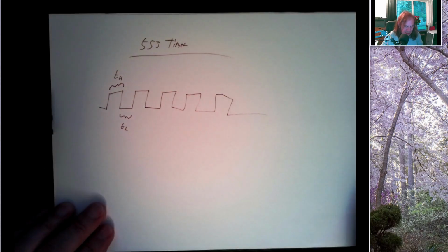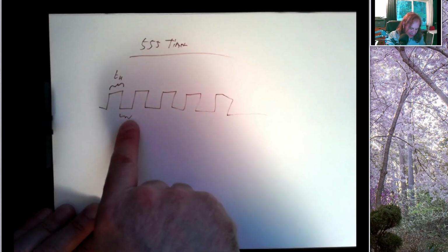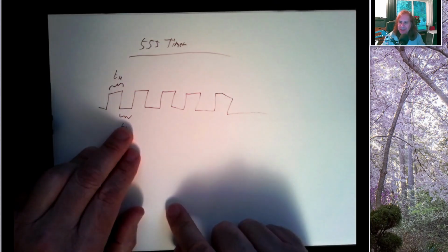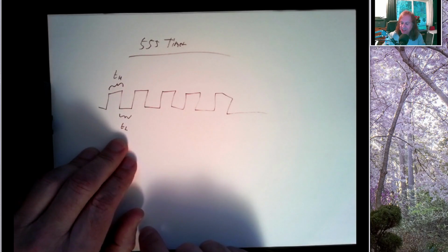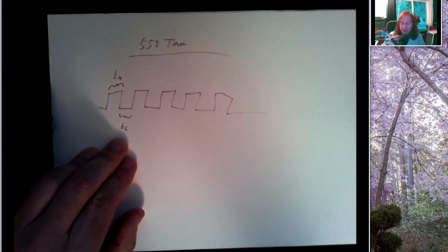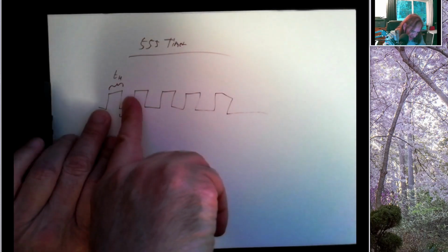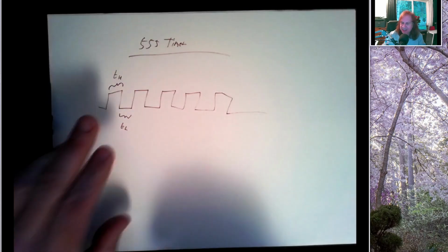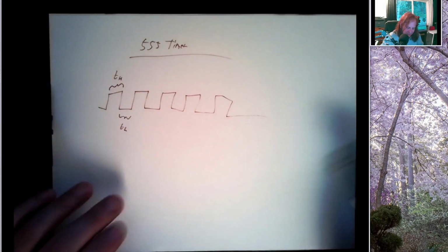For example, if we made this half a millisecond and made this half a millisecond, we would be going up and down a total of 1 time every millisecond. That's a 1,000 hertz, 1,000 cycle oscillation. That's an audible tone, right? It's about 1 octave above a tuning A440, and it would sound like a buzzy kind of sound because it's a square wave. It's got lots of harmonics. We hear lots of higher frequencies in there, and so on and so forth.